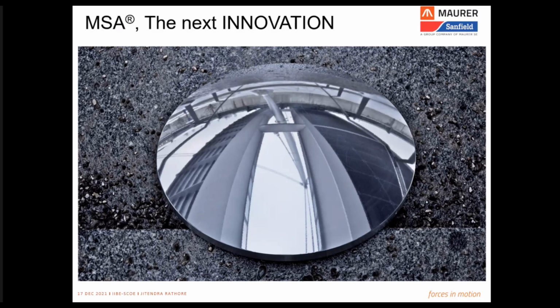It is no different. It is also made up of steel. So corrosion has been another enemy of bridge bearings. So there has been innovation in this direction also. Now there are certain improved aluminum alloys which have been developed, which can replace the traditional and conventional steel components of the bearings, and these aluminum alloys are so made that they do not require any corrosion protection treatment on top of them.